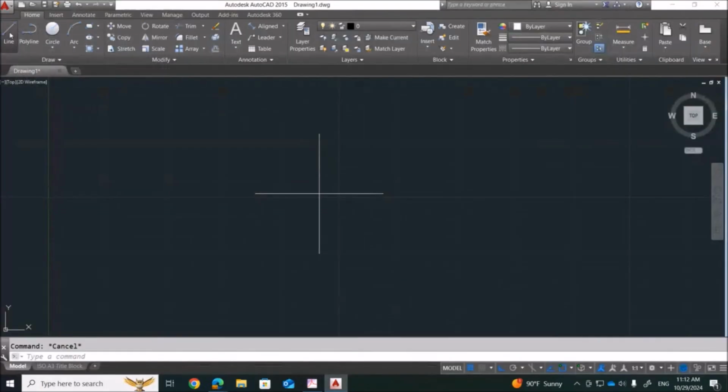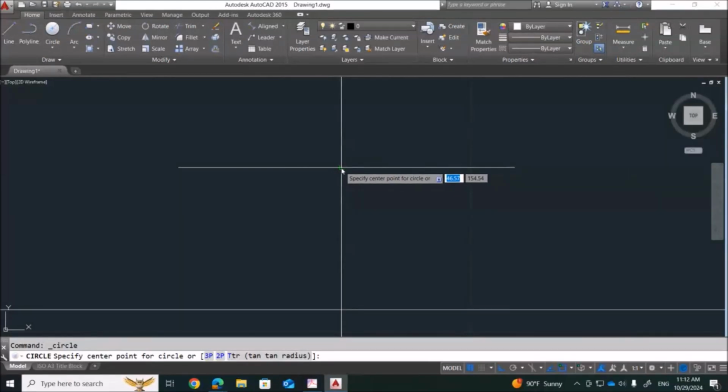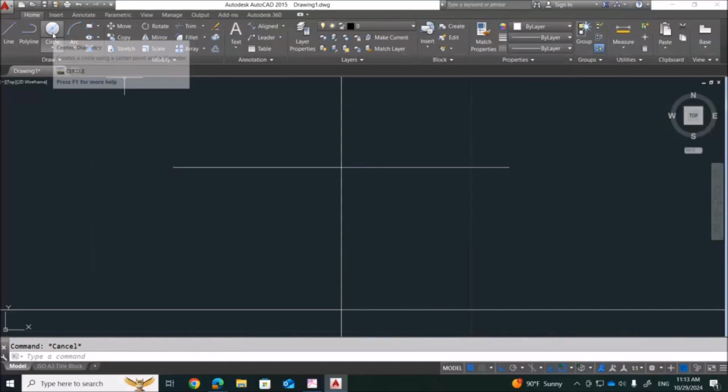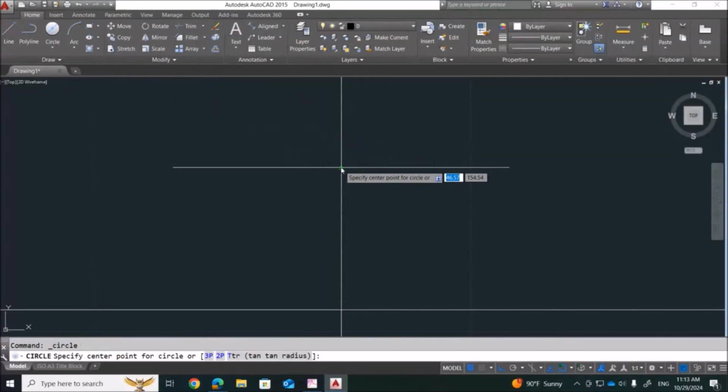So on the top view, I will make a center line somewhere here or anywhere, no problem, up or down. Circle with a diameter, select here and try to see. Some student will make mistake here. This is midpoint. No, I want intersection. I want intersection, see. That's why I always told you make it on the line. Yes, then it will be correct. So this small mistake will become big later on. So take care of these things.